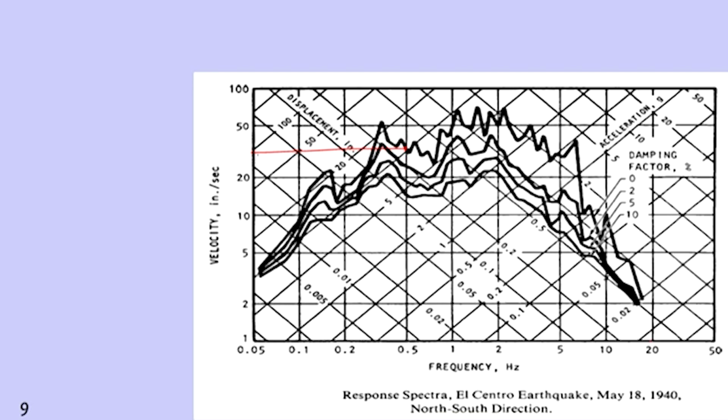So we need to read it like that only. And now, how to get displacement from this one? From the same point, on the 45 degrees line here, we can directly drop a line perpendicular to this 45 degrees line. Then you measure displacement. You can see values here: 0.1, 0.2, 0.5, 1, 2, 5 like that. So we can read this as the displacement value.